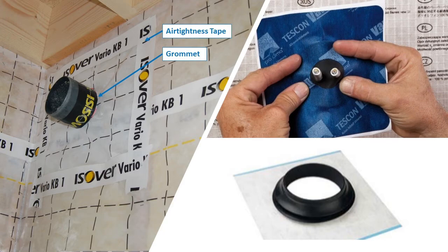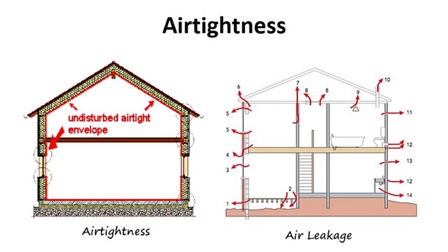There are many approaches possible to achieve an airtightness barrier which would meet the different low energy building requirements, but it is more important to understand the concept rather than all the different approaches. In order to eliminate air leakage, there needs to be an unbroken airtightness barrier around the internal of the house. If there is a leak in this airtightness barrier, then there is a path from the inside to the outside and air leakage will occur. This will result in the warm air escaping and cold air infiltrating inside the building.